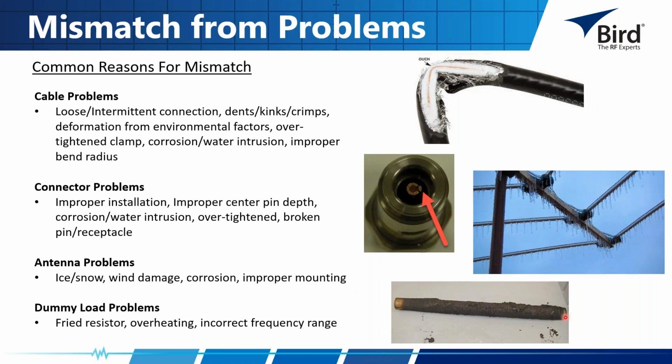Some guys are overpowering them, ending up toasting these things. You'll see impedance start to drift over time on different loads just from heat and shifting around, especially in something like an oil load that's going to have these chemical components in it due to the oil that's inside.